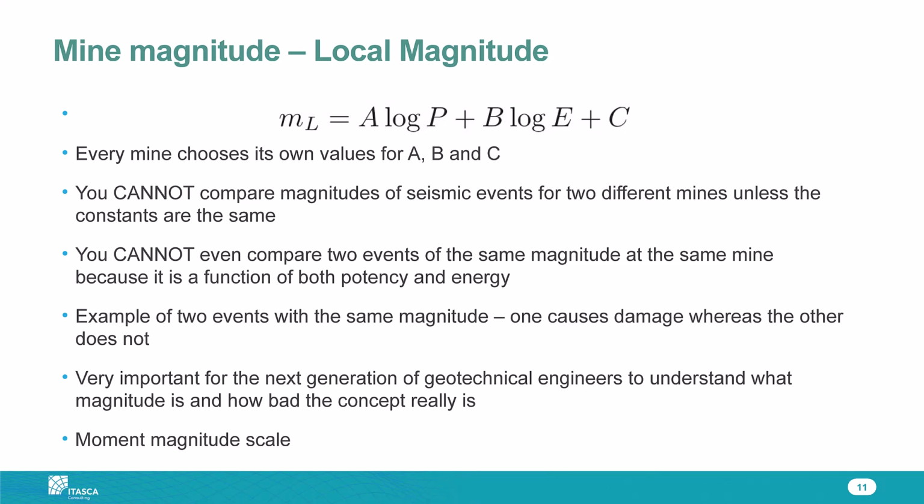There's typically that classic slip type event on a structure close to mining excavations. That's stress driven. That one typically has higher energy, and that will be more damaging. On the other hand, if you're in an event that's got more potency, more inelastic deformation, less energy, it typically means that the event occurred maybe in a lower stress region or already fractured rock. So that's why we observe less damage. But again, both events can equate to magnitude 2.